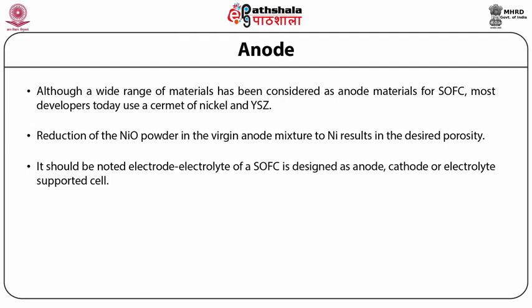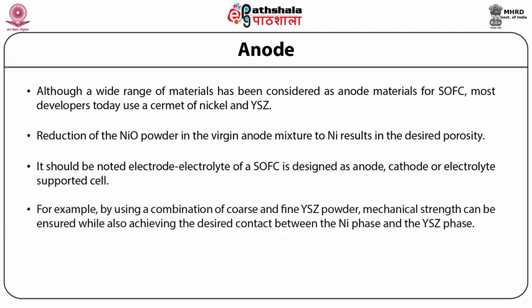Of these, anode supported cells are more common and successful. For example, by using a combination of coarse and fine YSZ powder, mechanical strength can be ensured while also achieving the desired contact between the nickel phase and the YSZ phase.